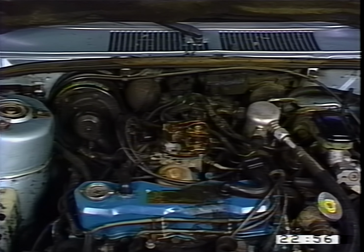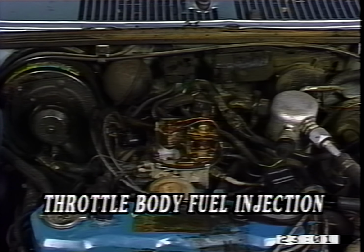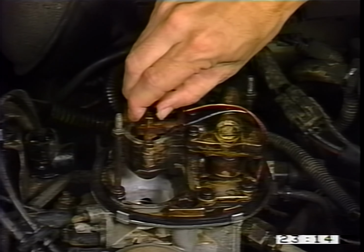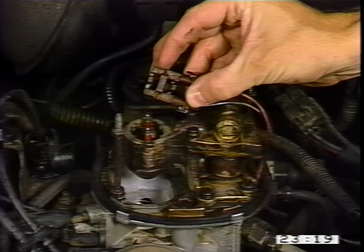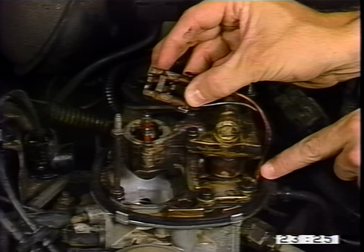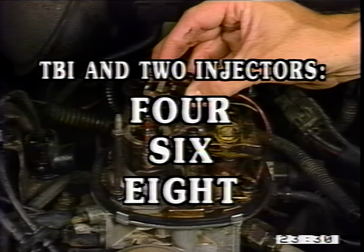The other type of fuel control used with the C3 system is throttle body fuel injection. Throttle body fuel-injected models have an in-tank electric fuel pump, which provides fuel to the injectors through an inline filter. The pump supplies fuel pressure in excess of the vehicle requirements. Situated in the intake manifold-mounted throttle body housing is an electrically pulsed injector, which makes up the throttle body injection system. Injector on time is controlled by the electronic control module, which regulates fuel to the engine. The throttle body fuel injection is available on 4, 6, and 8-cylinder applications.